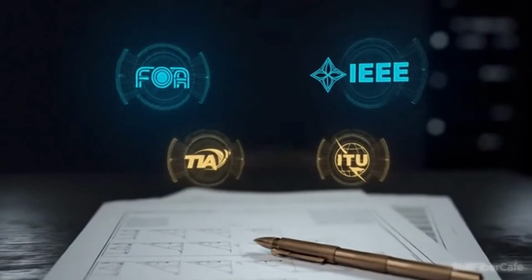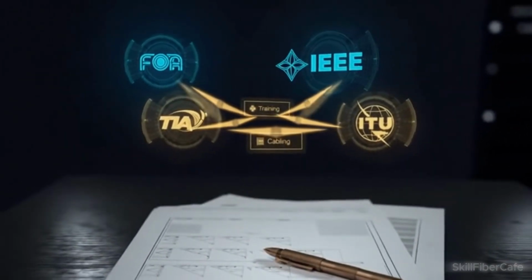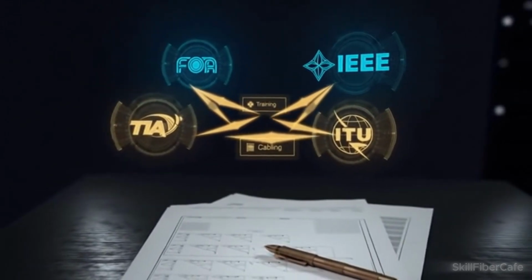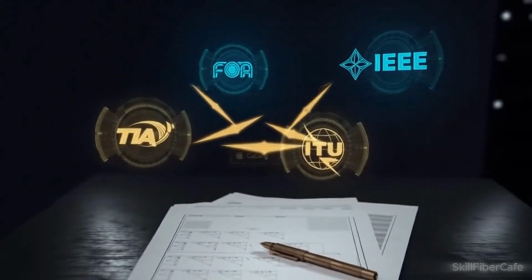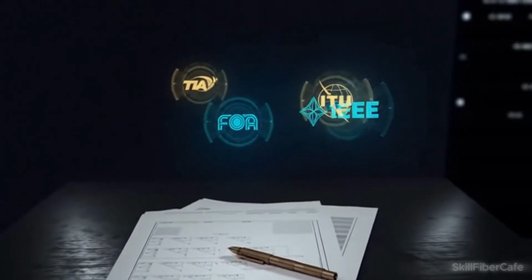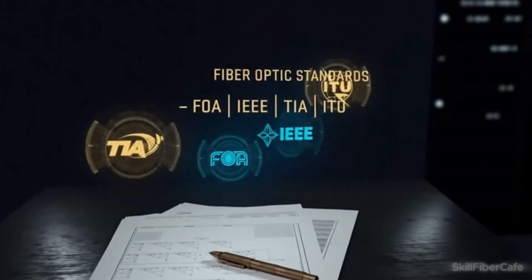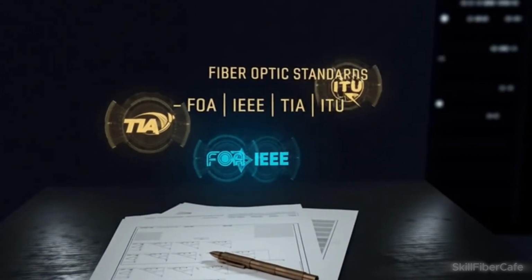Global standards guarantee interoperability and reliability. FOA oversees installation and testing. IEEE 802.3 defines data protocols, TIA 568 structures building cabling, and ITU-T G.694 governs DWDM and carrier-grade optical transport.